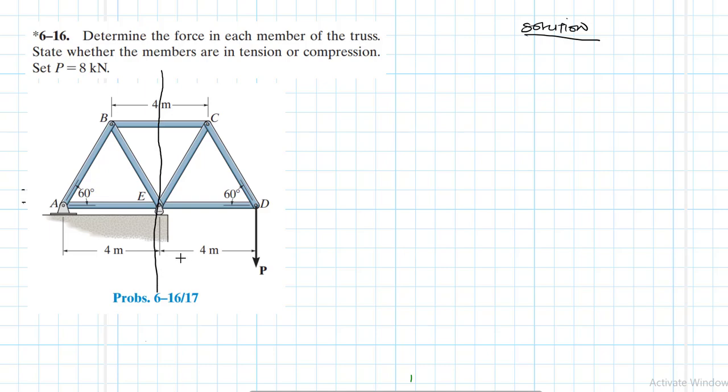Okay, so that is one step. Let's check on the loading. I could have started directly. When you look at joint D, we already have a loading there and the number of unknowns at joint D is 2, so I would have gone directly to finding the member forces. But I've realized that there is symmetry in this, which will make the work much easier.